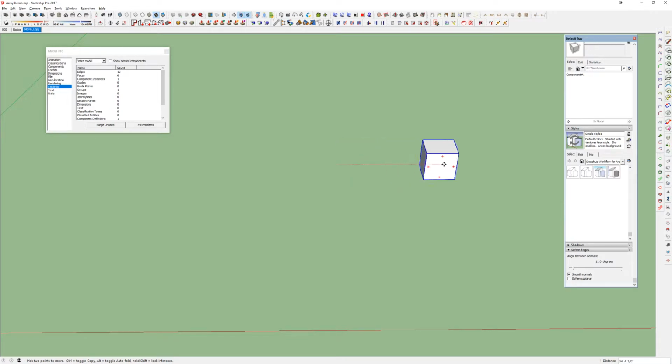Even if I move it again, and you can see this moves 40 feet, and I click to let go, since that distance is still there, if I don't hit escape and don't do anything else, I can type in 120, and it moves it back to its proper move of 120. So there are two ways of doing this. I can either move it, not click, type in, say, 240 for 20 feet, and it moves it 20 feet.